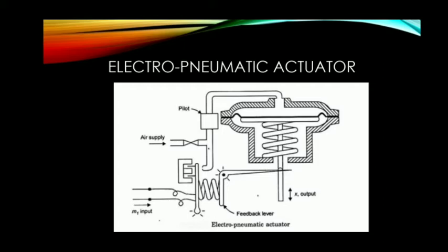More often the valve actuation reset is achieved by pilot-assisted solenoid actuation to reduce the size and cost of the valve. Control of an electro-pneumatic system is carried out either using a combination of relays and contactors or with the help of programmable logic controllers, PLC. A relay is often used to convert signal input from sensors and switches to a number of output signals, either normally closed or normally open.